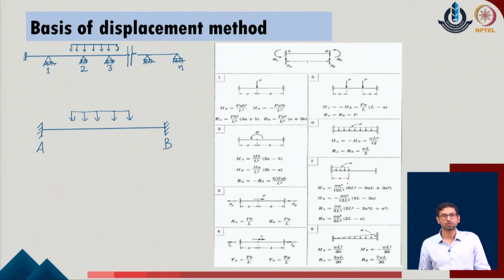At the same time, we also now recall that for all these standard cases on a given member, as we are considering that fixed ended members subjected to some load can have the influence of the end reactions only on the given span. So, that is why we now go back to some of the standard results which we evaluate in the force method for the standard fixed ended reactions of the kinematically indeterminate systems and take the help of those to analyze the systems using the displacement method.